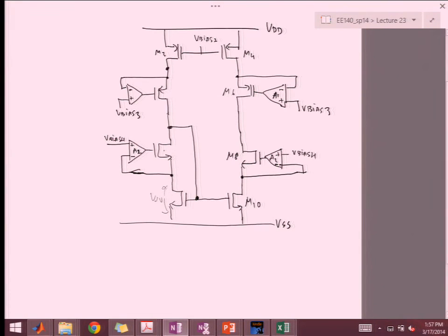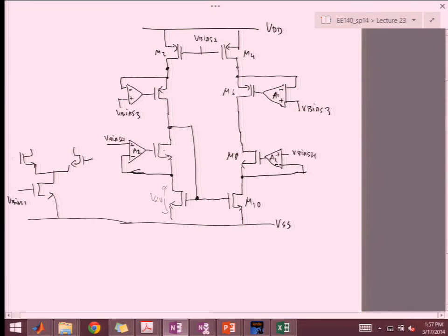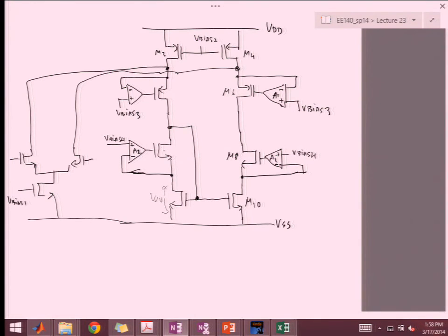And then since these are the cascoded nodes, I'm going to take my input, and then move one here and another over here. Okay, I hope I got all this right. Yeah. So this is our circuit. Okay. So each of the cascode transistors is now gain boosted. There's another expression for this, which is gain boosting. And then I take my VO over here.